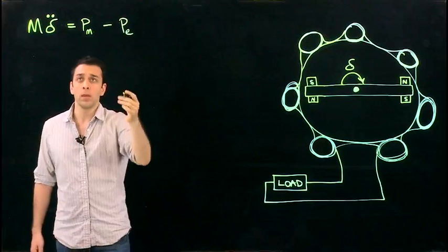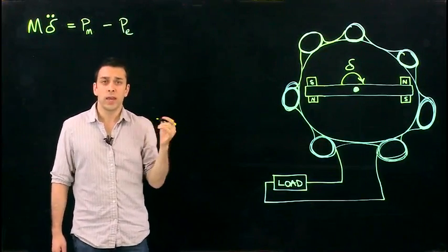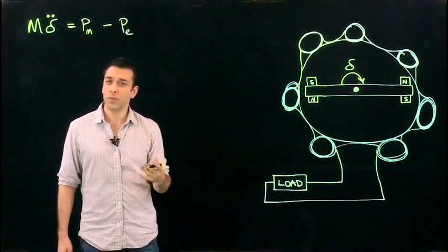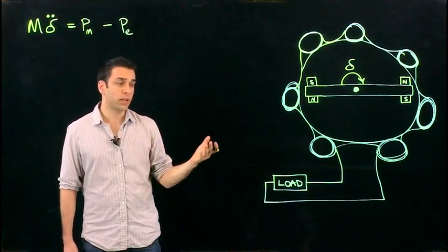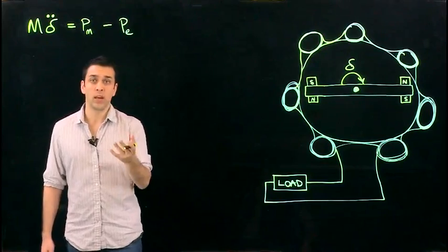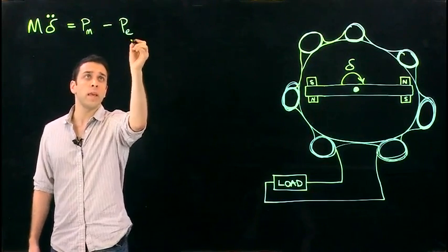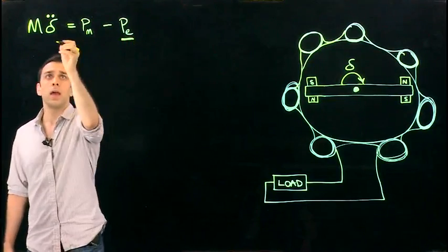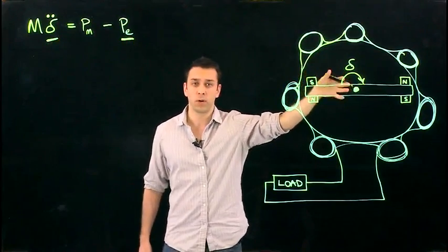So two things that you should be noting from these swing equations is that, first off, they're very simple second-order differential equations, yet they provide good enough approximations that they're used by actual power engineers in modeling the power grid, which is surprising and great for us. The second thing you should notice is that they really make it apparent the connection between the electrical power and the acceleration of the rotor of the generator.